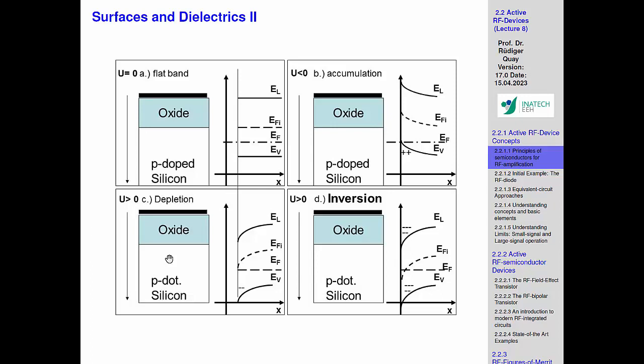So that means by pushing the p-type carriers away, we are generating some others. And that is good, because if you do that strongly, and this is exactly what we do in a MOSFET, we suddenly create, here we're just pushing away carriers, but we suddenly create near the interface carriers of the opposite type. So we have electrons in a p substrate. So this goes up.